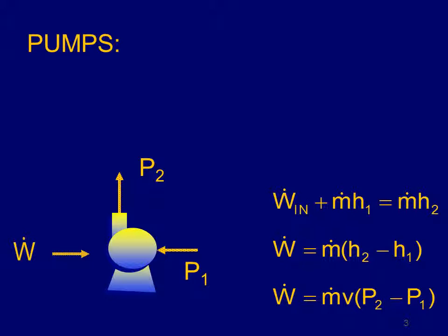in enthalpy. Here we're neglecting velocity, and for liquids which are very dense, the velocity is going to be relatively small, very small really, compared to the mass of the fluid that's flowing through and the energy associated with the pressure. So we have work flow is equal to mass flow times specific volume times P2 minus P1, because you recall for a change in enthalpy, where it's just mechanical energy, the work is V delta P, and that's what we're going to use for a pump.